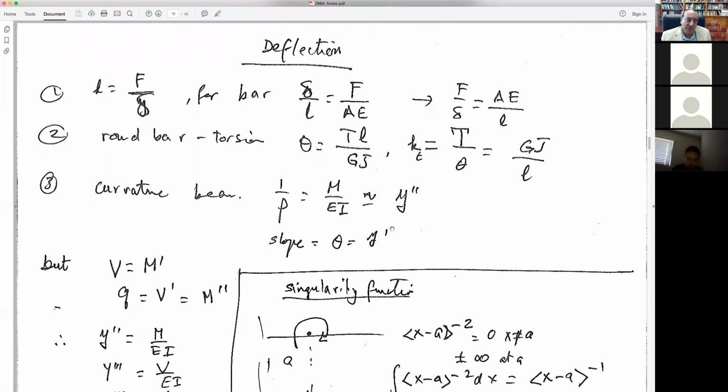Next, so now we summarize materials, we summarize stresses. Now we're going to summarize deflections, because that's the second part of the design: material selection, satisfy stresses with some kind of failure criteria, satisfy deflections and rotations. So for deflections, we define the stiffness constant K as F over delta. And our goal is to go over every element and find that stiffness.